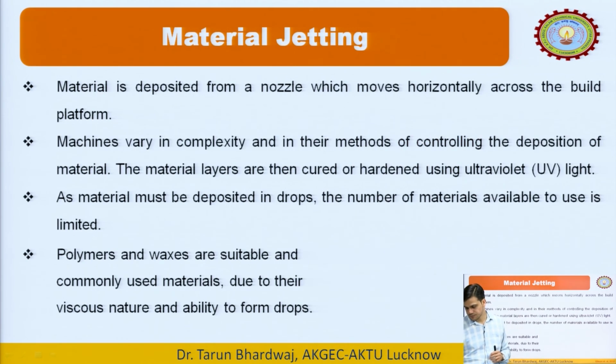Okay, now material is deposited from a nozzle which moves horizontally across the build platform. Okay, and the machines vary in complexity and in their methods of controlling the deposition of the material, and the material layers are then cured or hardened by UV light. As the material must be deposited in drops, the number of the materials available to use is limited.